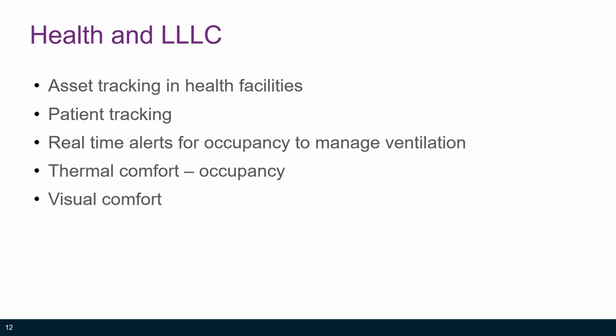Thermal comfort management from LLLC occupancy sensors can be better tuned and more responsive than thermal management by carbon dioxide sensing. Visual comfort and sensibility can be better addressed with the granular control of luminaires as opposed to that of zonal control.